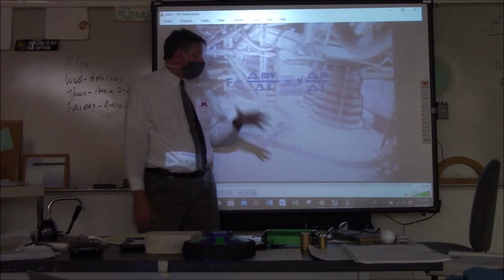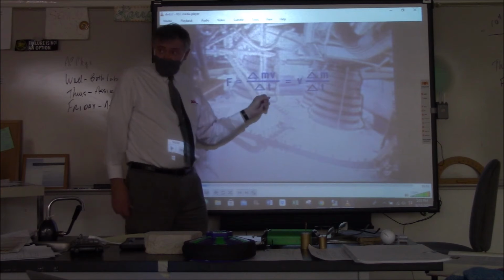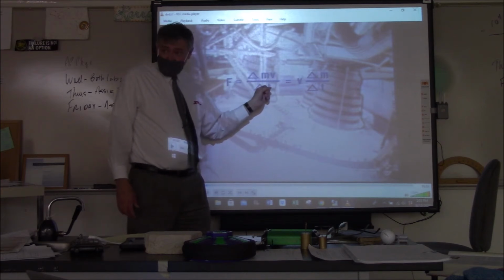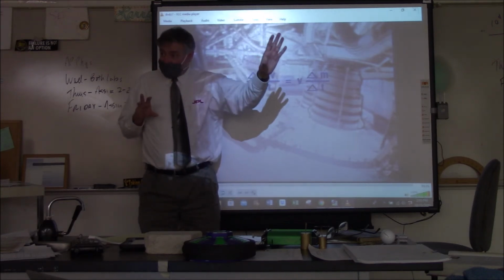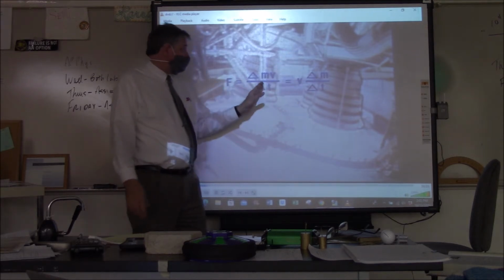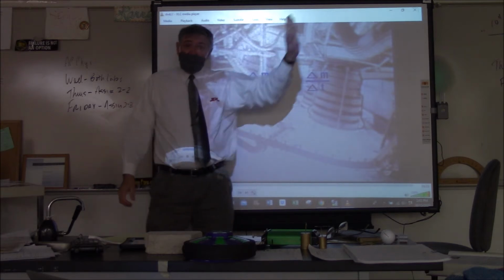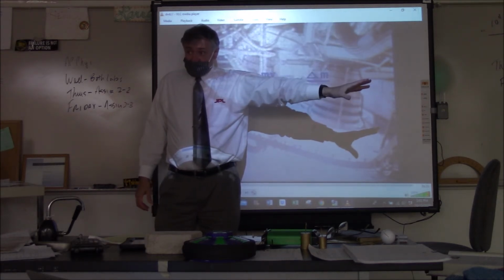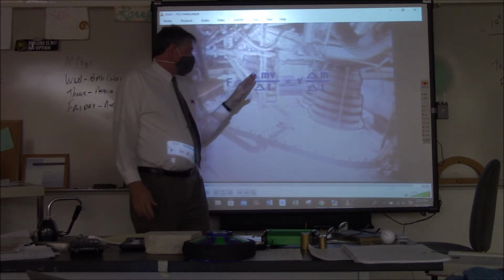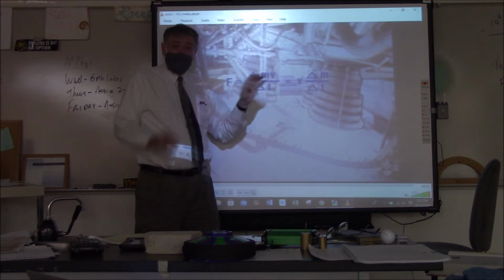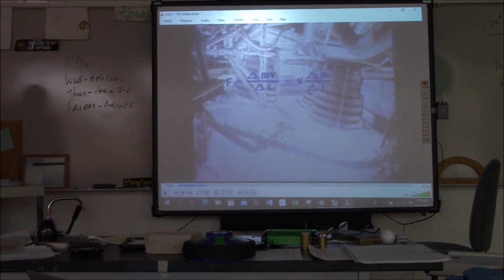of the escaping gas. So basically, if you want a really powerful engine, you want to consume a lot of fuel, which is this change in mass per unit of time, and then you want that fuel, that burnt gas, expelled at a very, very high rate of speed. So the more mass you can consume per second, and the faster you can get that gas out of the back of the engine, the more force that you're going to generate. So this is why these rocket engines are so big. Big change in mass per unit of time multiplied by big velocity. That's how you generate force.